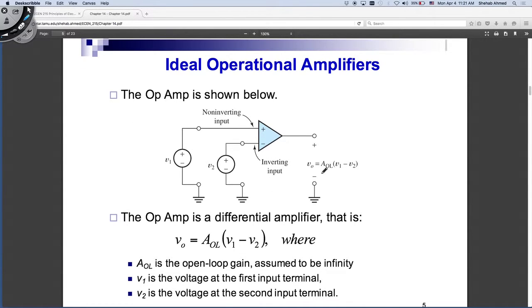What else? So this is the output voltage. We said that one of the main things about op-amps, and transistor circuits in general, an op-amp being nothing but a complicated transistor circuit, is that they do not require input power to be very high. They are actually looking at your input signal and taking the output power from the power supply connected to this op-amp device. So another characteristic, besides the open loop gain being infinite,